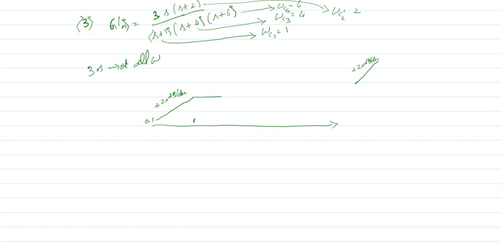Okay, then 2 is coming. After 2 the numerator term will function, right? So another 20 dB until 4. At 4, the denominator term will start functioning, so again it is 0.